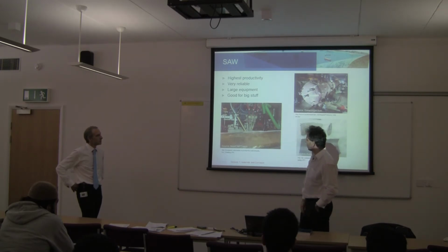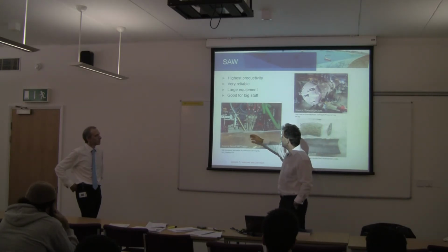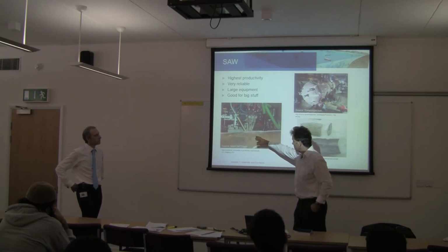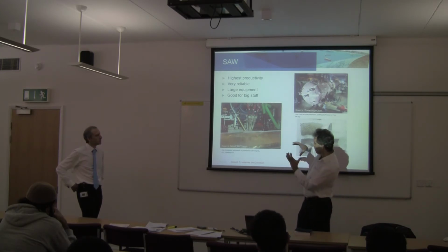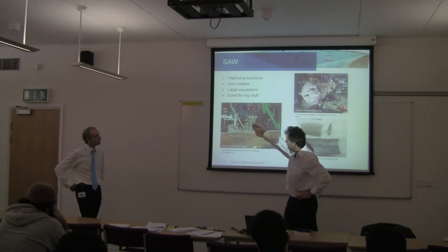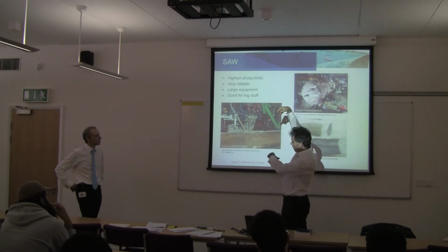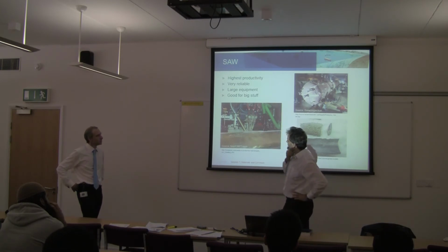It solidifies with a beautiful structure which has good strength, and in actual fact the weld is at least as strong as the pipe itself, and it can take the full pressure that the pipe metal alone could take. You do that all day every day, making large diameter pipes. But obviously this is a very automated setup. And this process, unfortunately, can only be used downhand, because it's a very high power, high current process. In any other position, gravity would make the metal fall away. So a beautiful high productivity process, but limited to factories, unfortunately.